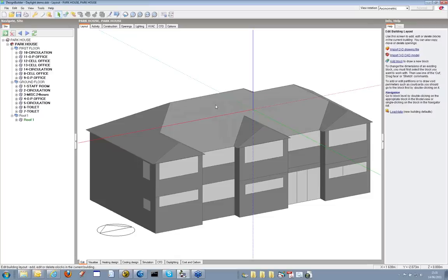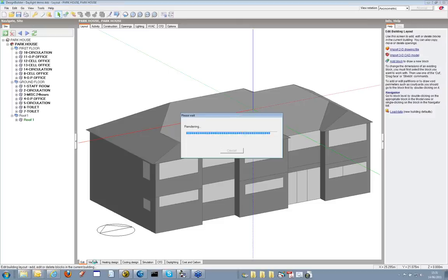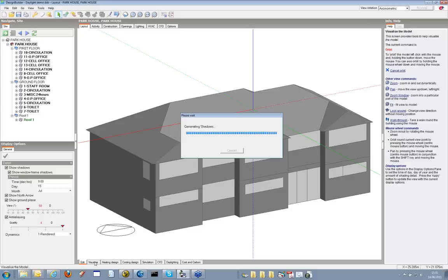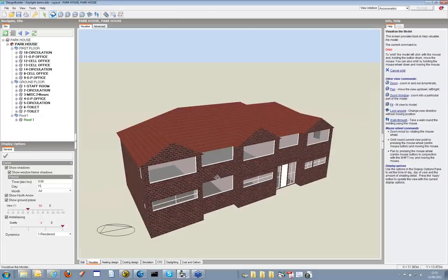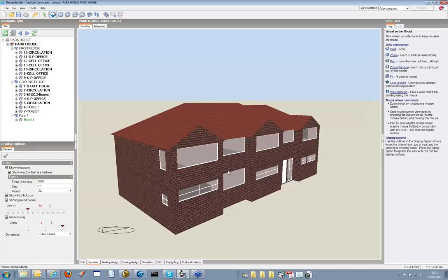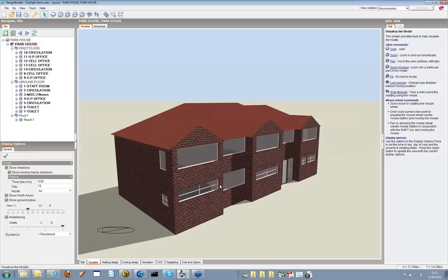Essentially, the way that the calculations work is that you can use any existing DesignBuilder model. All of the data that's required as input to Radiance already exists in any DesignBuilder simulation model. So what we're talking about here is obviously the geometry, and actually the geometry that's used in Radiance is based on the same geometry that you see in the visualization screen, rather than the simplified geometry that's provided to EnergyPlus. So you get all of the details of the dividers, the thickness of the walls, etc., etc. So yes, the geometry is provided to Radiance.